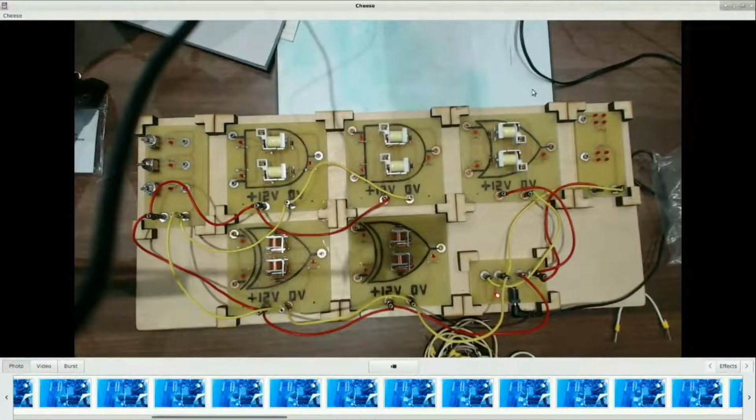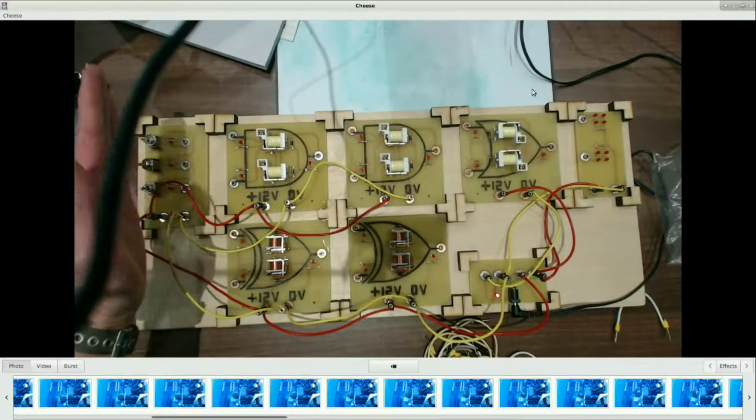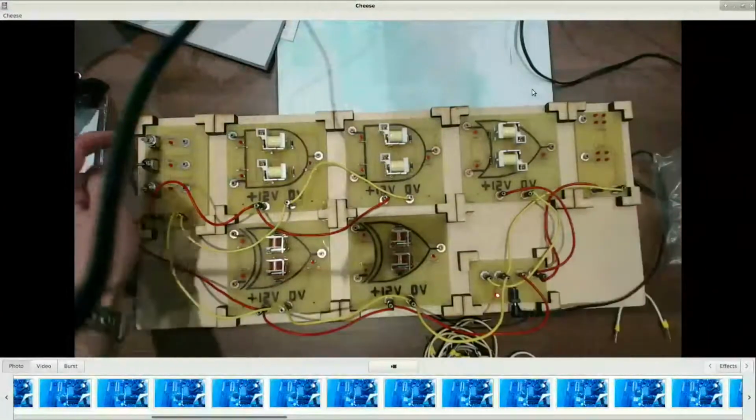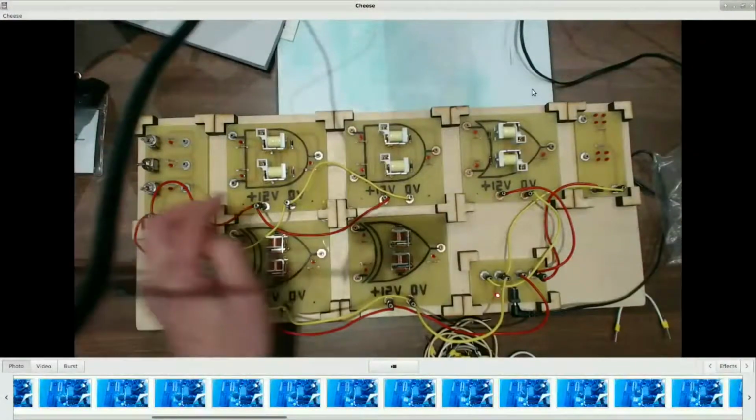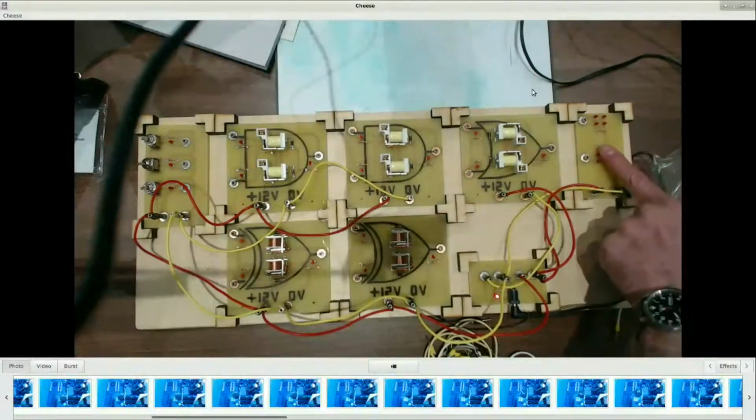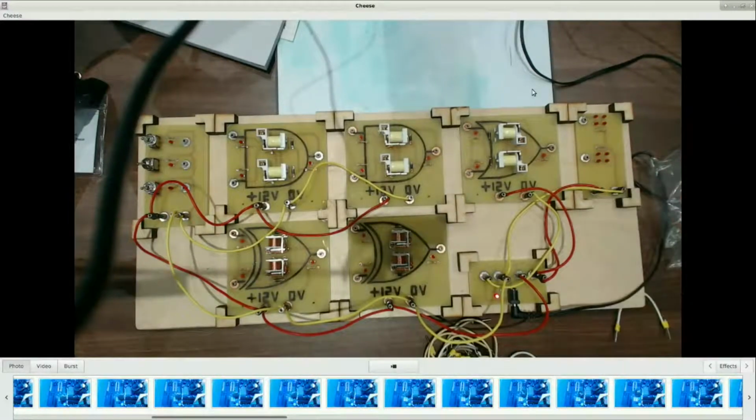So when you're laying out your schematics in ISE, start with your inputs and work across to your outputs. So here I've got my 3 inputs, A, B, carry in, and my sum and my carry out going across. When you're designing your processor for the open assessment, you'll be building different circuits. If all the wires are higgledy-piggledy, you will have great difficulty debugging it, so make sure it's nicely laid out. There are no marks for presentation in that sense. If it works, it works. But debugging it can be a pain.